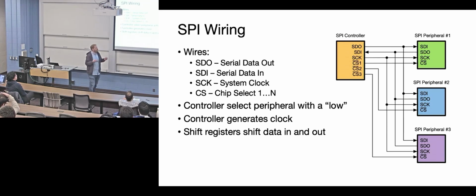Almost any microcontroller now will have a combined module, a peripheral that can do UART, SPI, and I2C, and you're usually just configuring it. The IP is so easy to make now that it's everywhere. But that also means there's a lot more flexibility in this one. We'll talk about it in a second. Just something to remember about this particular one.